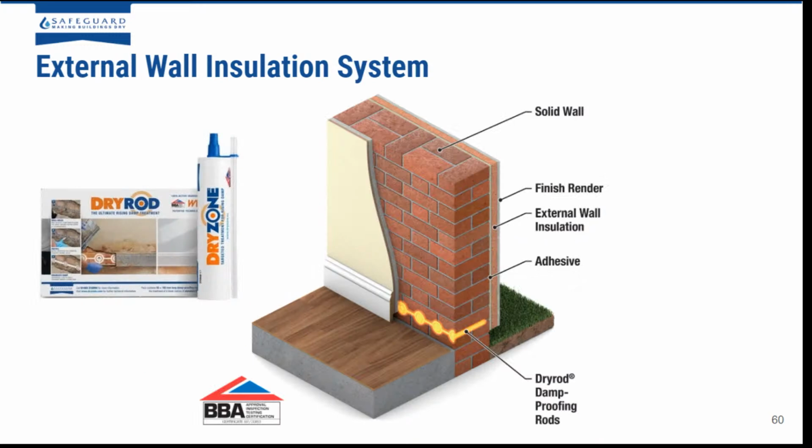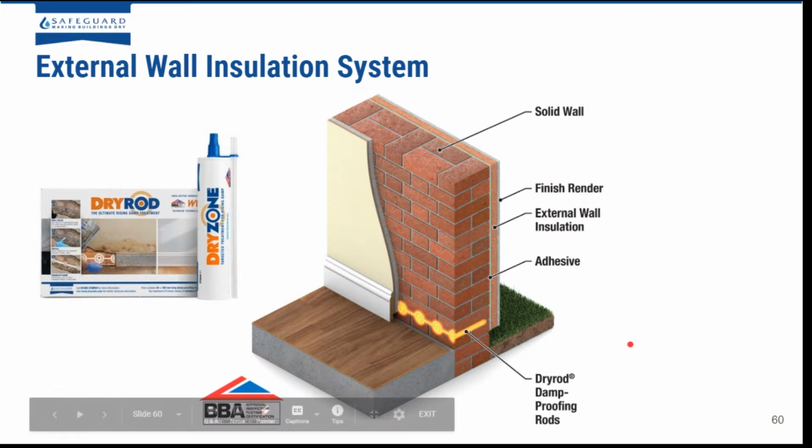Okay, so a moisture robust EWI system kind of looks like this. We make sure you install it correctly so you're not getting penetrating rain, and then install a retrofit DPC using either dry rod or dry zone cream.